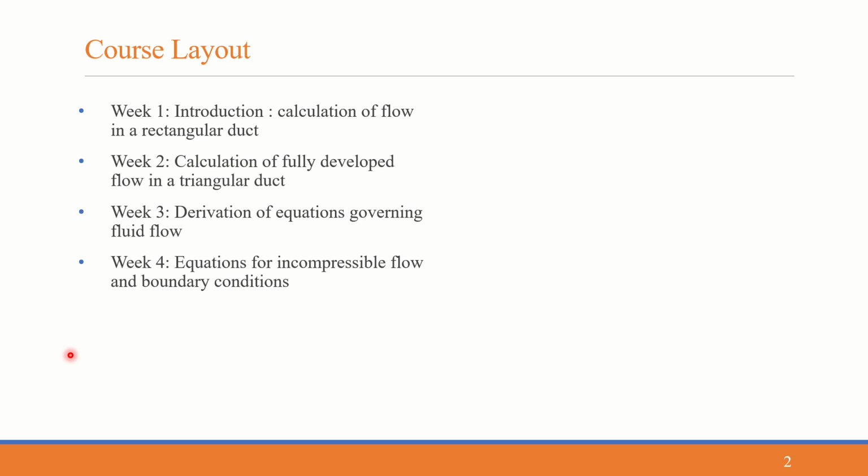When we talk about CFD, we are solving equations, but we need to know certain values beforehand. So consider the problem of a fluidized bed. Here we need to know the inlet velocity, that is the fluid inlet velocity, or a basic application like a flow of water in a pipe. We are giving it at a certain velocity, the inlet velocity. So that is one boundary condition.